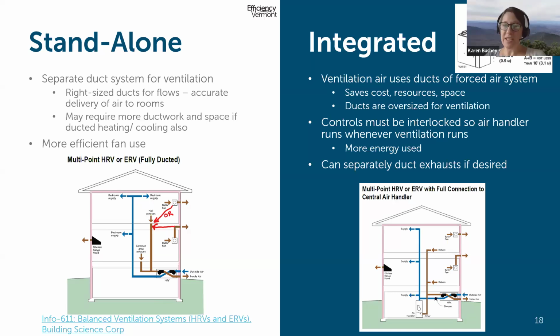So. And Mark and I were talking about this before, how you have to know that you can't actually power off your HVAC system, because if you turn the switch off, then obviously that air handler won't be able to run. So you won't be getting any fresh air delivery. Right. If the ERV was running without the unit running, it would just short cycle inside the ductwork, because you're taking air in here and pushing air out here. Without that system fan moving it through, you would just create a really short cycle in your ductwork.